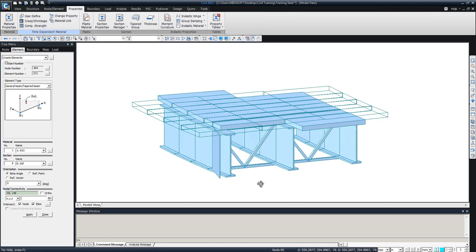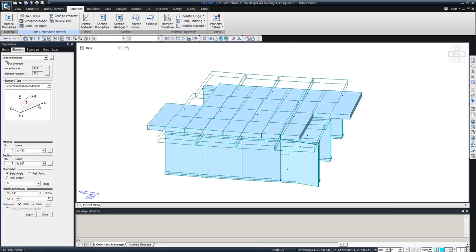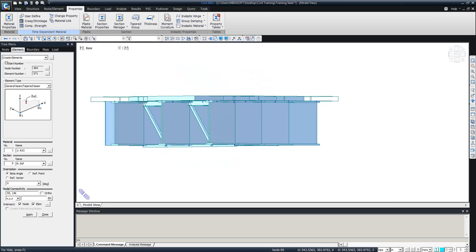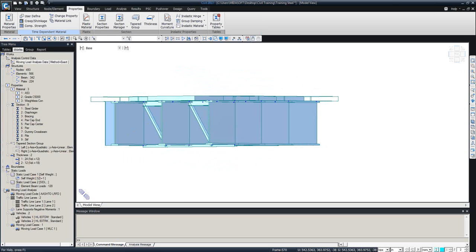Okay, the direction went wrong, but it's going to be some element right here, stiffener. But probably if you model these with the plate element, then the stiffener makes more sense because it's going to work along with the element. Here, to simulate that stiffener, I just connected the top and bottom of the girder. But yeah, we can simply model those stiffeners. That's the short answer.